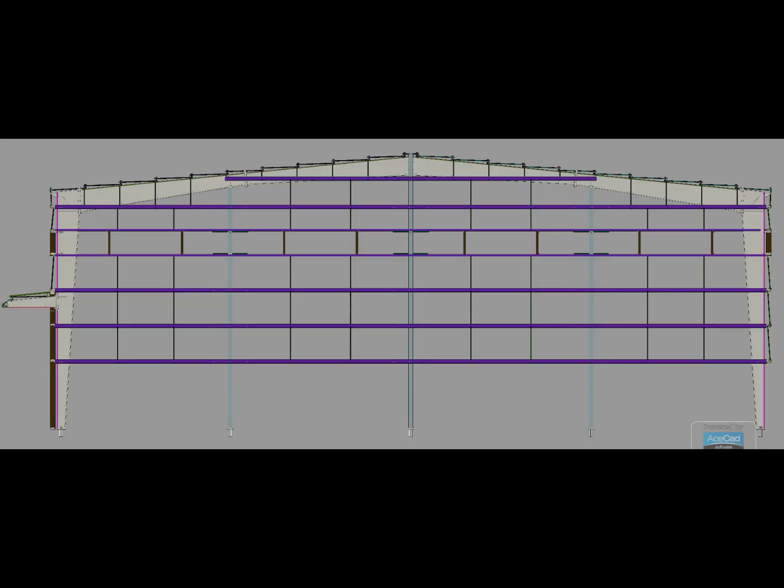So, in this slide, we identified the sag rod location in the end wall framing of a real PEB project. We saw the main end wall columns, the horizontal framing members, the roof profile, and the slender sag rod arrangement within the framing. The main lesson is simple. Do not ignore the small members in a PEB drawing.